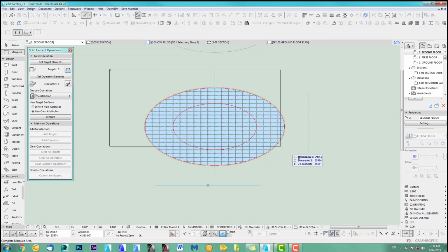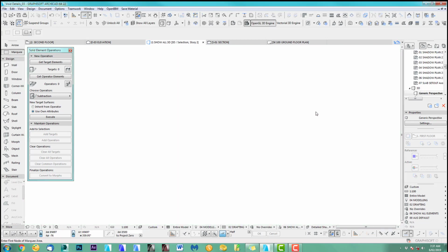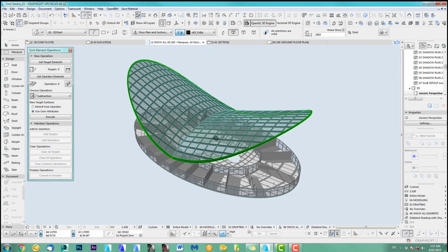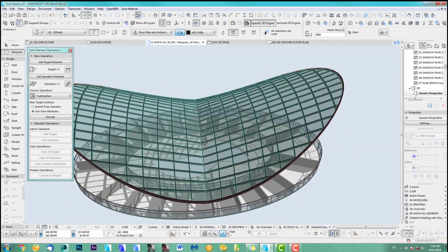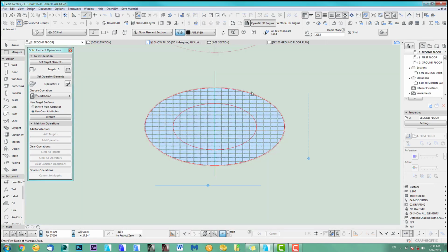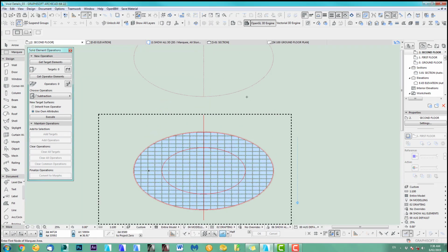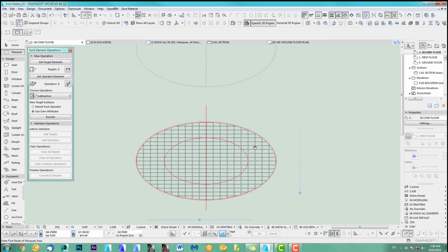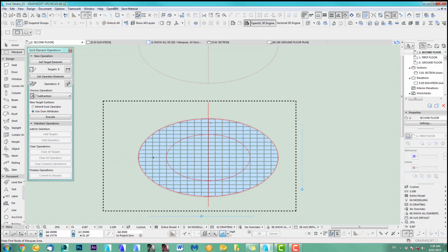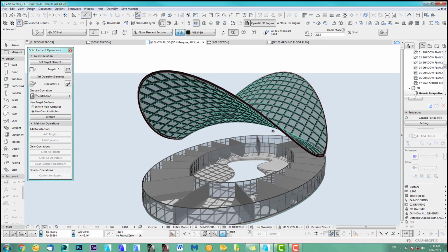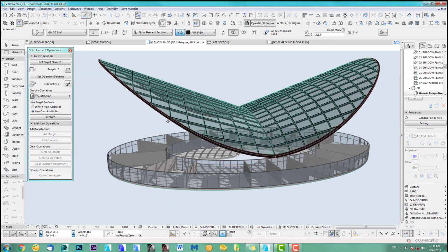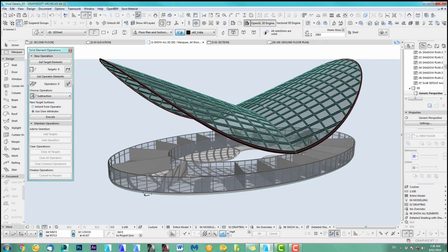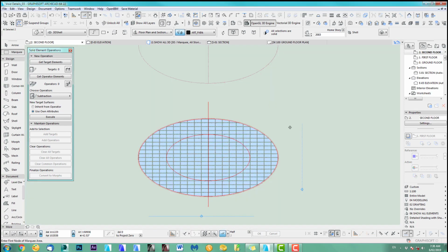This is gonna look good. There you go. Beautiful frame along here. Excellent, excellent. So, like I said, this one is on cutting element layer, or on any other layer you want to turn off, so that's fine. We have to still add another slab and some more curtain walls. All right, that's the next bit we do.